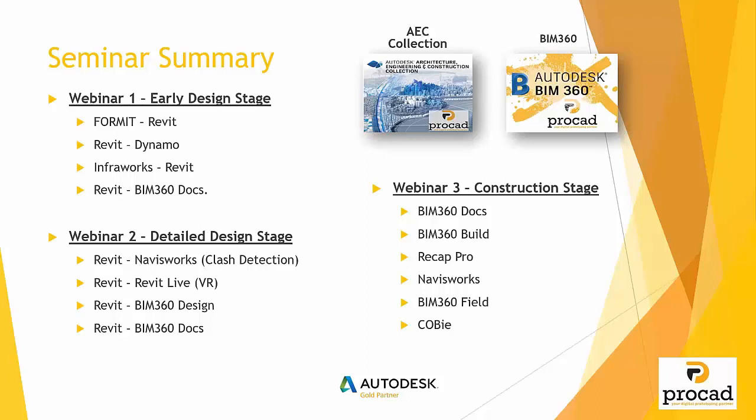And then we focused on Recap Pro, and we showed Navisworks being able to provide a 100% accurate model at the end of a project. In some cases, the client could say, I want to see a report proving that your model is a 100% graphical representation of what's built on site. That's just providing a Navisworks report where you have run a clash detection between your final point cloud scan and your final asset model. And then you start reviewing the COBie information to show that the actual items have information embedded in them.